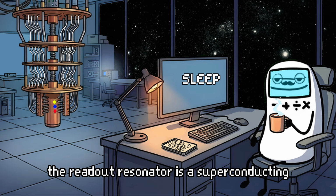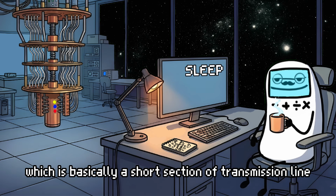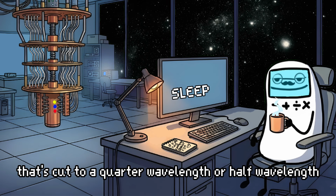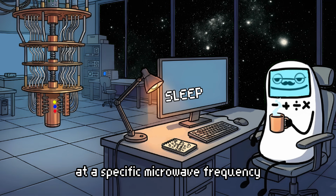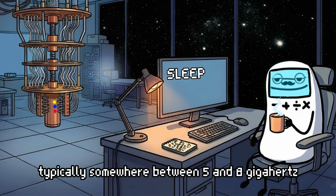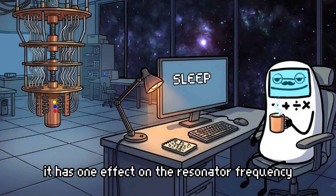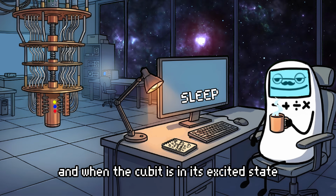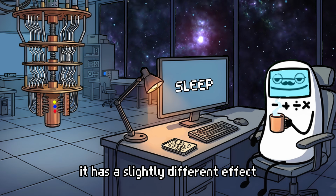The readout resonator is a superconducting microwave resonator, which is basically a short section of transmission line that's cut to a quarter wavelength or half wavelength at a specific microwave frequency, typically somewhere between 5 and 8 gigahertz. When the qubit is in its ground state, it has one effect on the resonator frequency, and when the qubit is in its excited state, it has a slightly different effect.